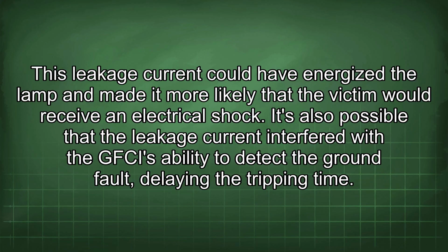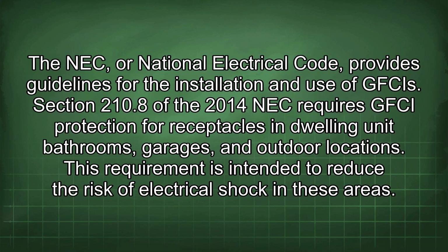The NEC, or National Electrical Code, provides guidelines for the installation and use of GFCIs. Section 210.8 of the 2014 NEC requires GFCI protection for receptacles in dwelling unit bathrooms, garages, and outdoor locations. This requirement is intended to reduce the risk of electrical shock in these areas.